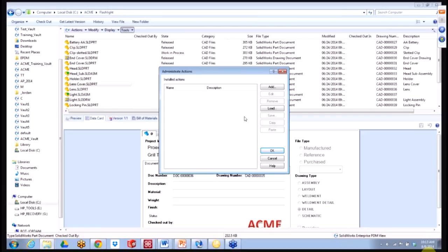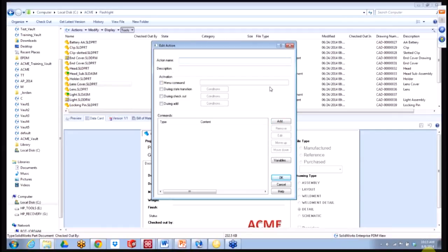And this is where you can start adding dispatch scripts. So what I'm going to do is add a new dispatch script. I'm going to call it rename file, and I'll put a dash dispatch, just so that I don't get it confused with the Windows function file rename. And I'll give it a description, rename set of files with serial number.